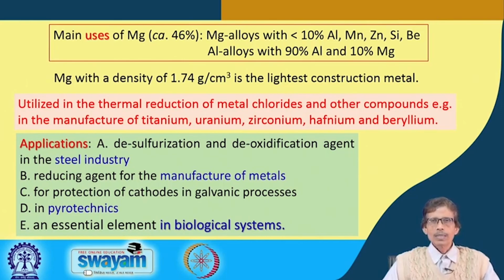It starts oxidizing and reducing, and the material which is your anode is getting corroded or decomposed, losing its life. For protection through that galvanic process, we know that we do this for the protection of iron samples. Similarly, magnesium is also used for the protection of some of these materials. A pipeline can be protected through connection with a magnesium bar or rod, because whatever destruction takes place through that galvanic process is on the magnesium, not on the pipe itself.